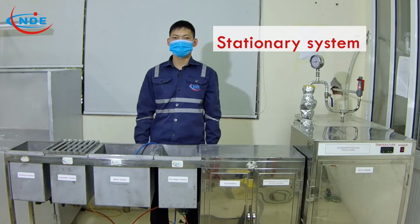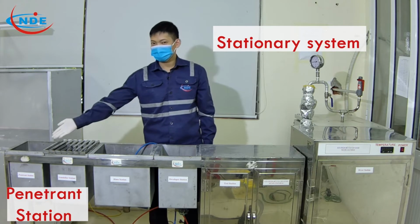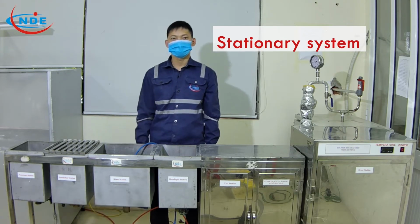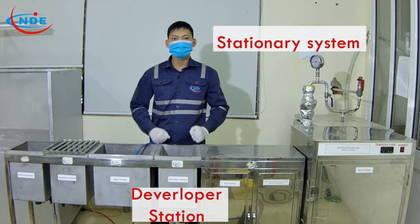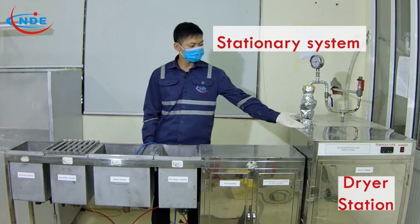Stationary PT system. This is our product under Science Research in 2017 with the title Research on Design of Stationary System for Liquid Penetrant Testing, done by Mr. Nguyễn Văn Duy. The system includes a penetrant station, rinse station, developer station, testing station, and dryer station.